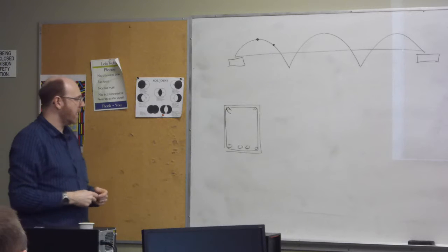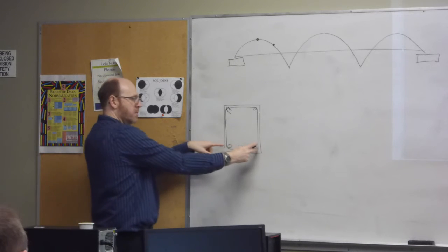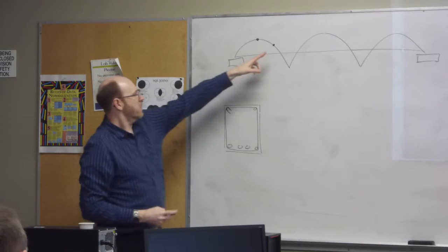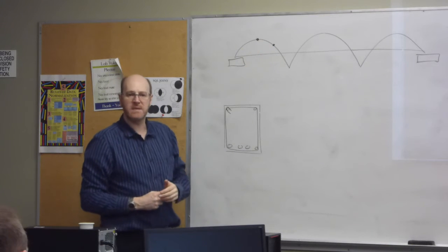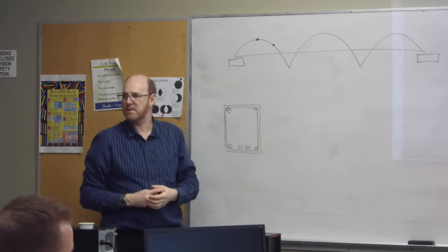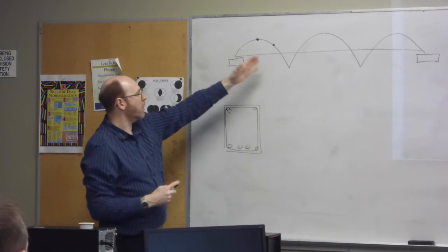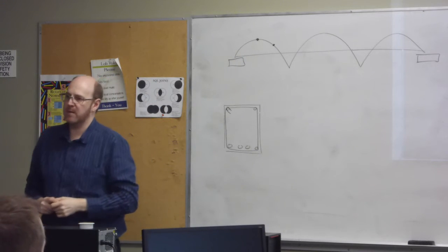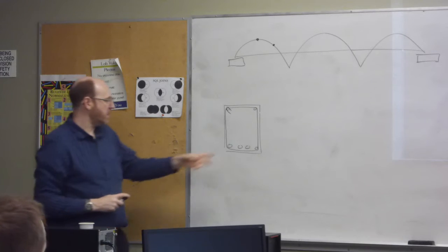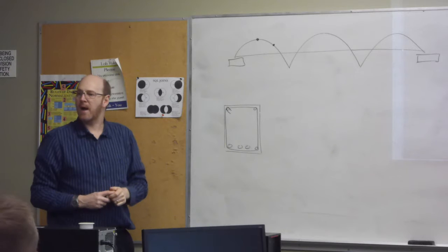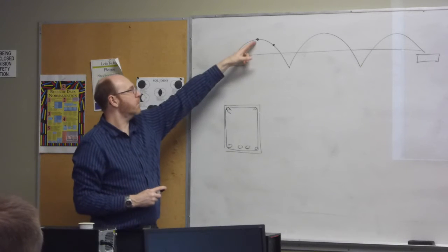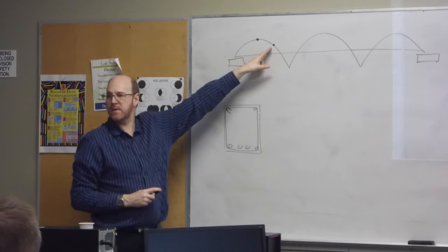So what I'm going to be looking at is, okay, if I'm starting with my minimum of a bar in each corner, then where does that fit with my moment diagram? What kind of moment resistance do I get with just those 2 bars? And then I'm looking at areas where I could put in additional bars. I might add 1 additional bar, I might add 2 additional bars, and they may vary. I may end up with 2 rows of reinforcing here and only 1 row of reinforcing there.